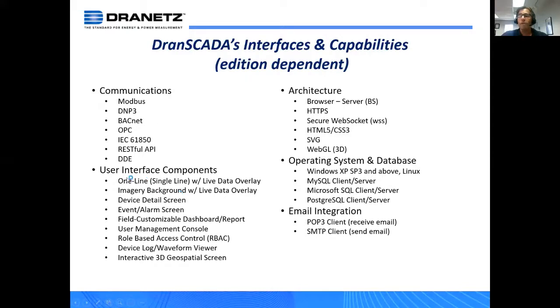User interfaces, a lot of people like one-line diagrams, which gives the electrical flow of their facility, overlaying real-time and breaker and PDU and branch circuit monitoring, whatever it may be. Background imagery, maybe pictures or photographs of your facility, even photographs of the metering, which terminals show, and other sorts of information about your facility, trending and alarming and meters.